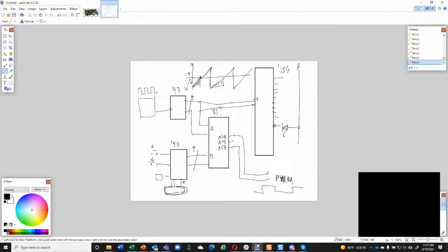You'd have your data input, and these are your enable outputs, 16 of them. And then you have this output enable, right? So if output enable is low, this works. If it's high, they all go to logic high, or 5 volts, and float. So none of the LEDs light up if that's high.